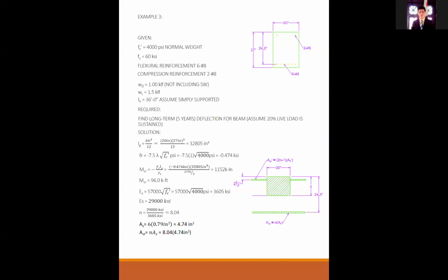Yes, I do. So, what does the y sub b represent in this case? It is the distance to the neutral axis. But the difference is, in homework 4, it's already assuming yielding, and the beam has long since cracked. In this one, it's barely cracking. The big difference is that this one is assuming that your materials are still acting elastically.